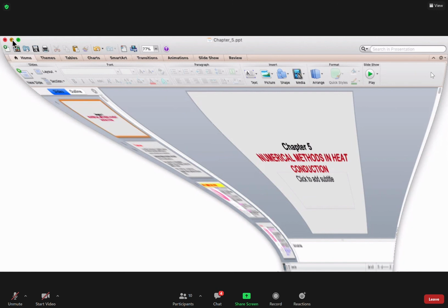Oh yeah, that's where we have to go to the table to find the eigenvalue and A. That's right. Table 4.2 or 4.3 is applicable only when the Fourier number is more than 0.2. Those tables give you the eigenvalue and the Bessel function values that you have here. But in this case, the Fourier number is lower than 0.2. How low is this? It's 0.1217. Okay, again, the person solved the problem if he was lazy.